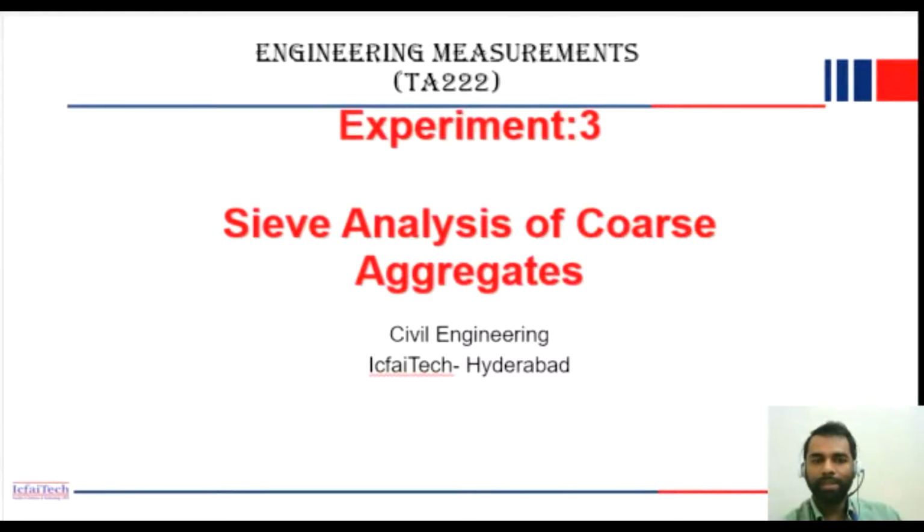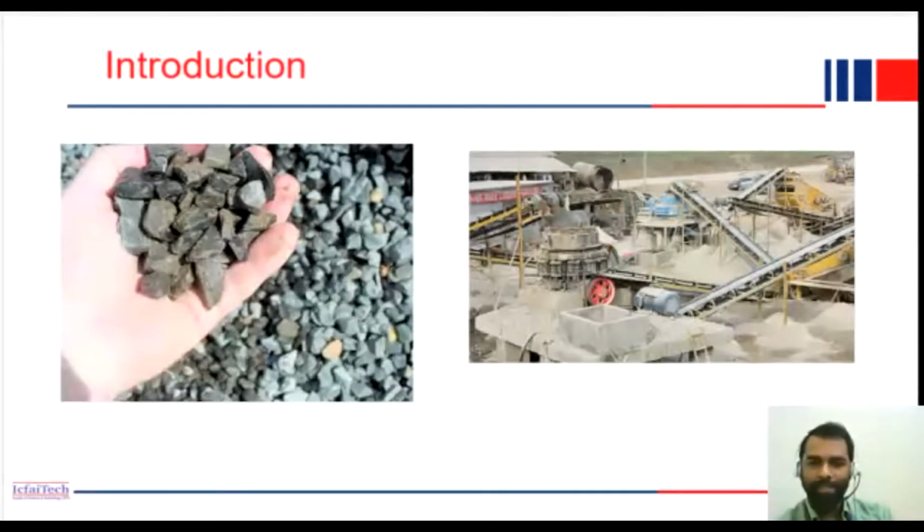Okay, so what we discussed is basically that we are finding out which type of aggregate it is, right? When you are constructing a structure, different beams and columns will be there, so each portion sometimes uses a different grade of aggregate. Sometimes we use 20 mm aggregate for foundation purposes. Then for the slab, we may use 12 mm aggregate. Even for highway construction, at the bottom of the highway we give large boulders. Similarly, for railway tracks, we give big boulders, 63, 80 mm aggregate. So how do we find out which grade of aggregate it is?